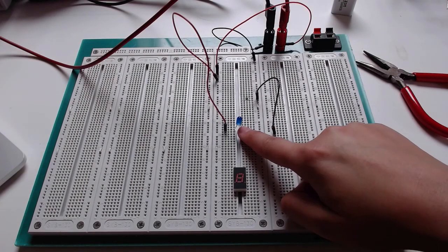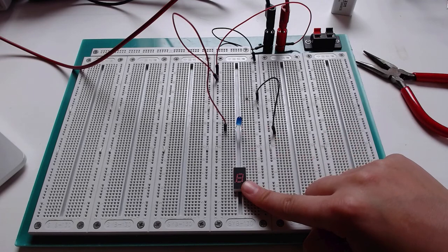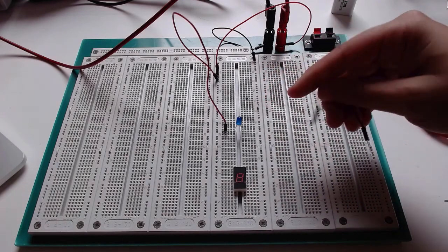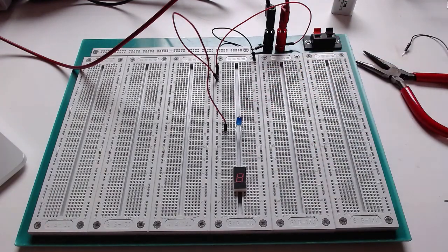So we want to make sure that we protect our LEDs, whether it be in a segmented display or just a standalone LED, by putting a current limiting resistor in series with this connection. So we want to know, where do we put the resistor, how large does the resistor have to be, and things like that. So there's a couple different considerations to make when you think about a current limiting resistor. We want to know what the smallest possible value of resistor can be, and then we can go from there.